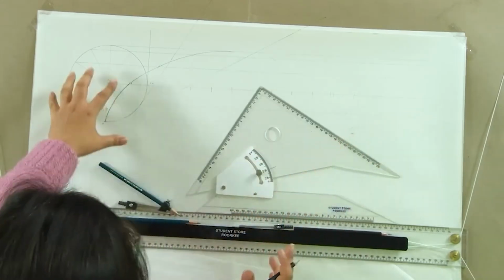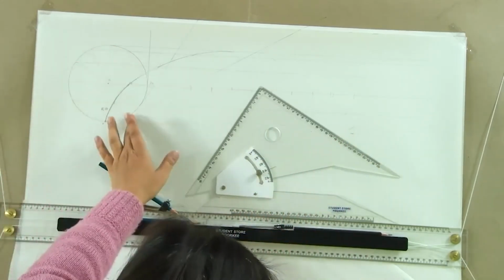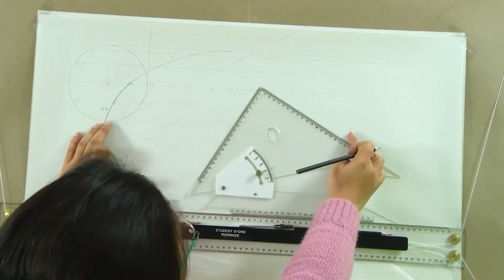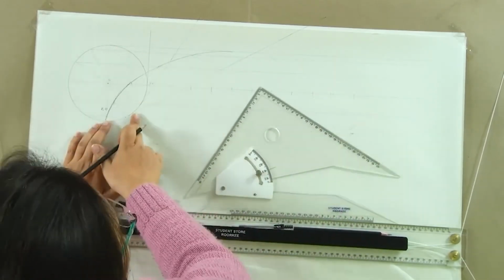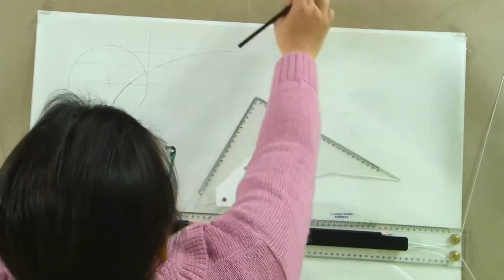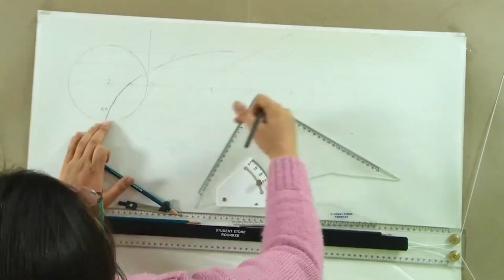For drawing the involute of the square, assuming there was a square here, we would draw 4 equal parts with the final length being equal to the perimeter of the square, and we would keep drawing tangents and start opening one part by one.